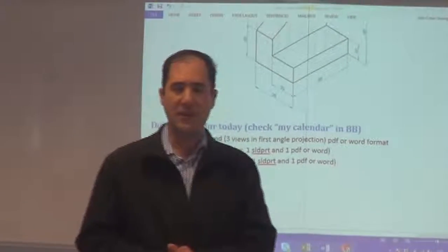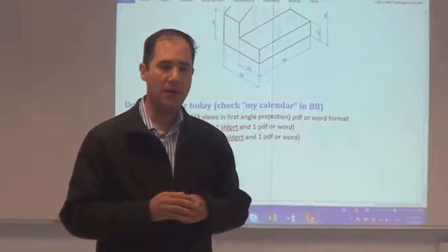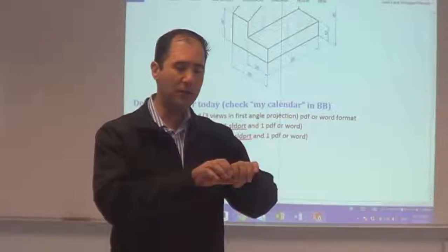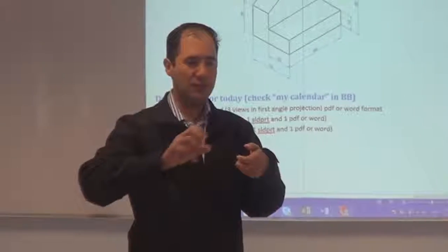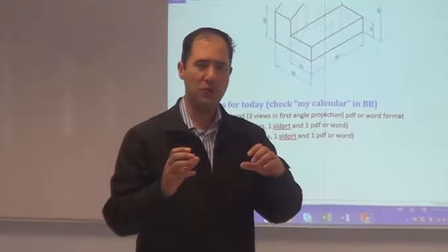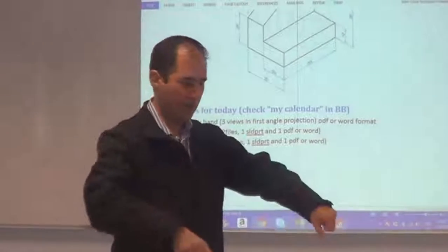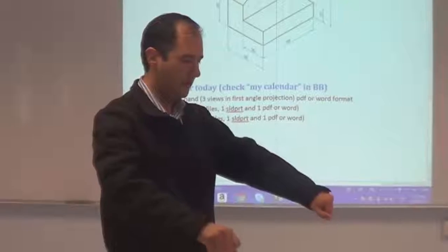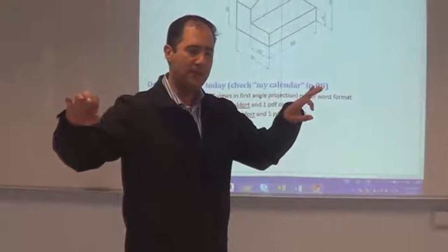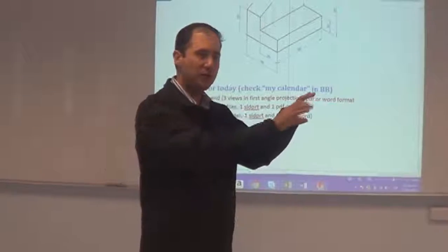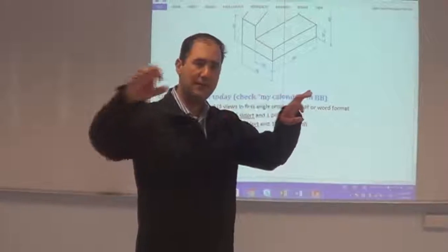Okay, before getting started, the sweep command. The sweep command is made for those geometries which cannot be constructed in a straight line. You need some kind of curves. For example, to construct a bicycle handlebar, it's a geometry that cannot be built with an extrusion command. You need a sweep command because you need to follow these complex, curved shapes.